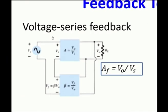feedback networks. It is a voltage series feedback. When you see the output side, the output voltage is given as the input. For voltage you have to take a parallel connection. In this way you take a sample of the output and give it to the input of the feedback network, and here it is series. So, the output of the feedback network is connected in series with the input voltage. This is very important. If it is series, the output of the feedback network is connected in series with the input voltage.